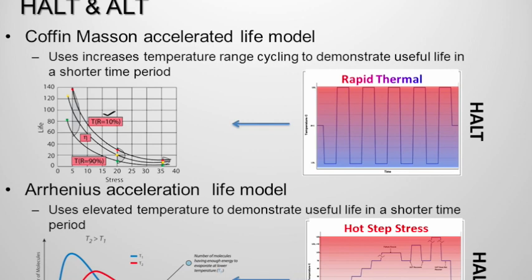Now, it's very difficult and not common, and I don't recommend trying to make a life statement based on the failure responses in HALT from this rapid thermal transition. But what have you learned? You've learned what these primary wear-out failure modes are most likely going to be. And you've gotten a feeling for the temperature ranges that create absolute destruction.